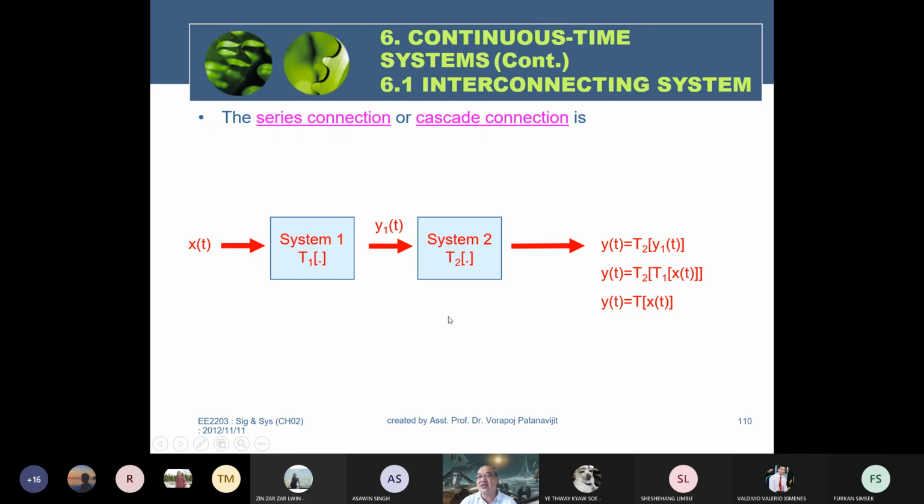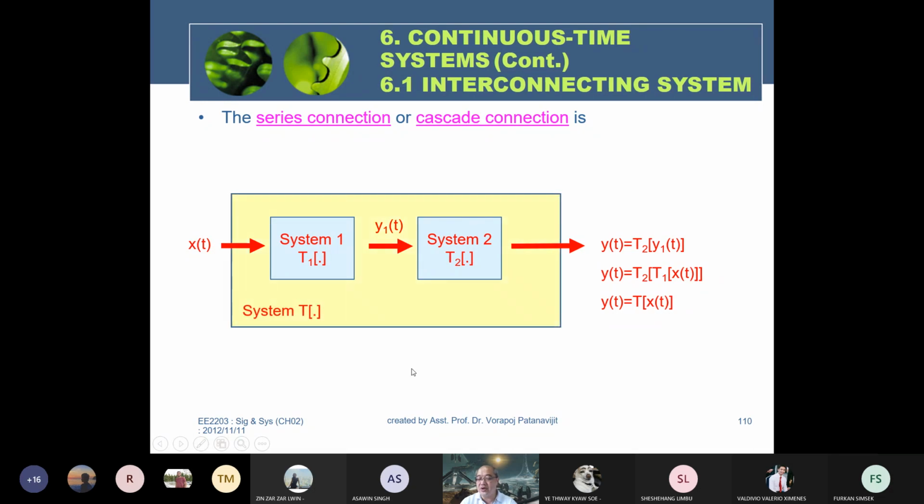Unfortunately, the signal generated from the microcontroller is only about 2 volts, which is too little, not strong enough to drive the motor. You must amplify it in an amplifier circuit first. Therefore, system 1 may amplify the signal generated from the microcontroller and send it to the motor later to control it. But from the engineering point of view, sometimes we don't want to know how many sub-blocks are in here.